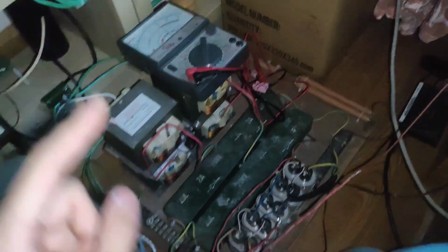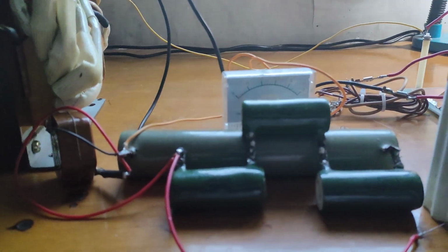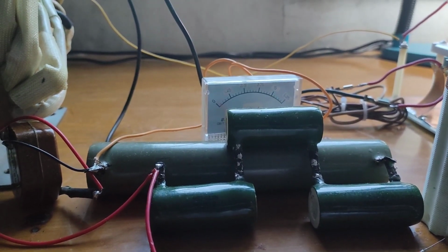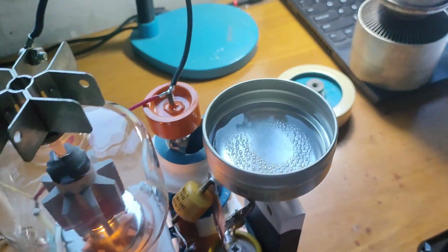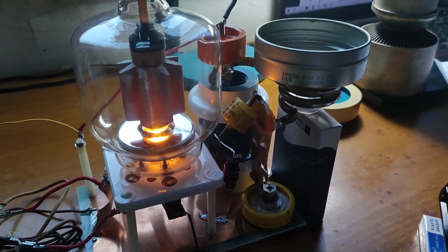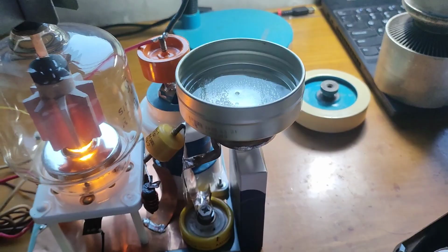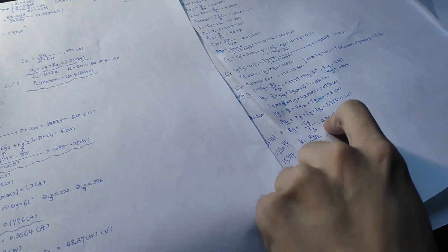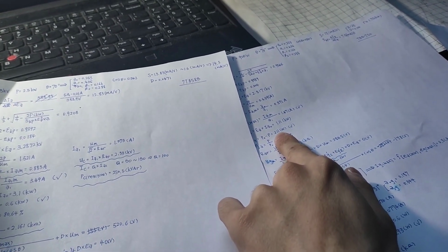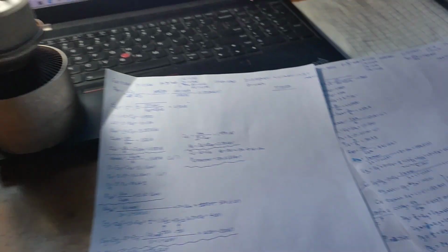Now it's 3 kilovolts. The cathode current is actually 400 milliamps. Oh, I turned the flash lamp off. Just 400 milliamps, and the grid current around 60, actually a bit less than 66 milliamps, and the room temperature water is actually going to boil now. The grid is just a little bit cherry red because the plate dissipation we calculated here is just over 200 watts, and this tube is capable of handling 350 watt plate dissipation.